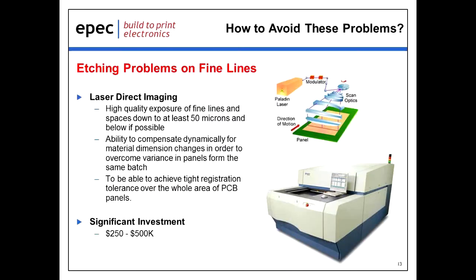So how do we avoid these problems? Well, looking at etching of the fine lines, which is the problem on the right on the previous slide, the etching process is pretty much based upon the quality of the image that you put onto the board before you do plating. Traditionally, we use dry film resist with a UV exposure, and that's been the process used in printed circuit boards for the last 50 years. While that works great until you get to about an 8 mil line, anything below that doesn't work very well. So several years ago a new process came out called laser direct imaging, whereby a laser is used